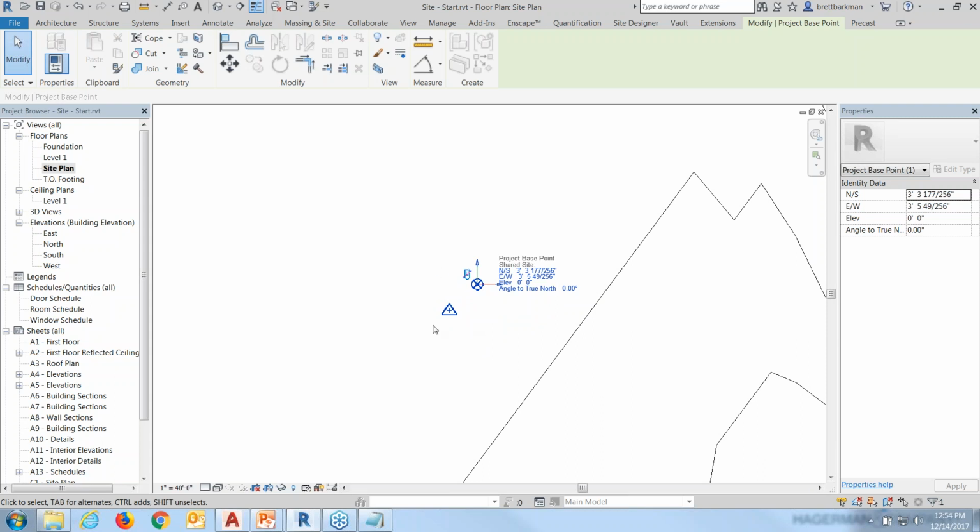I'm doing this just to show that there are 2 points in Revit. One is Revit's origin, which is actually the survey point, which we hardly ever mess with. And then there's the project base point. The 2 are not to be considered the same or treated that way. That base point can go anywhere. So I'm going to lay this right back on top here just so they're in the same spot. Leave it unclipped. And then for the project base point, let's highlight the elevation. I'll select it and change it to the same value I used for level 1, 792.